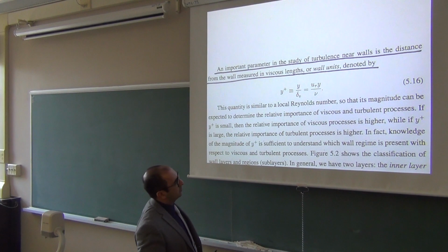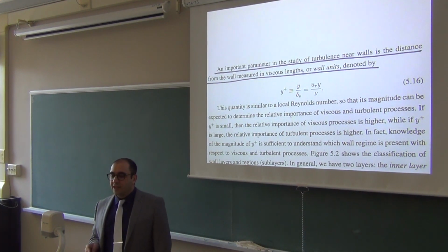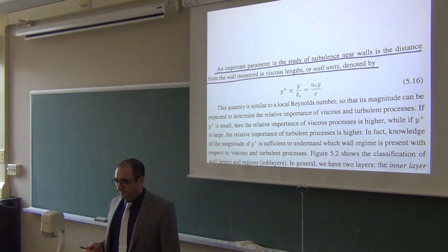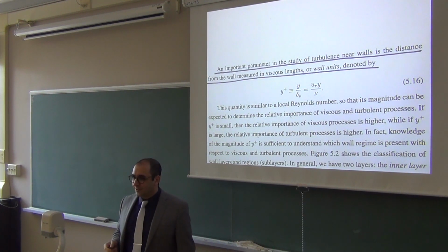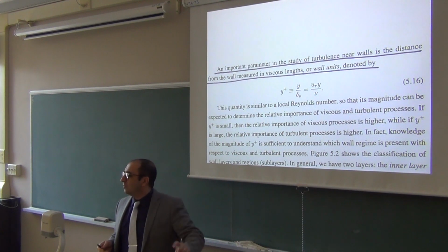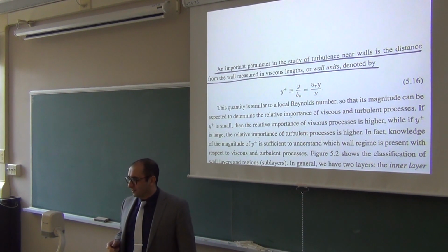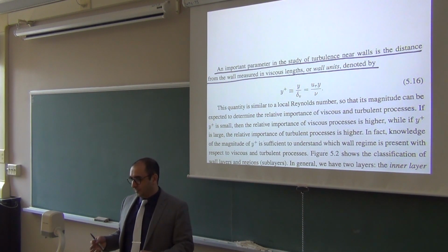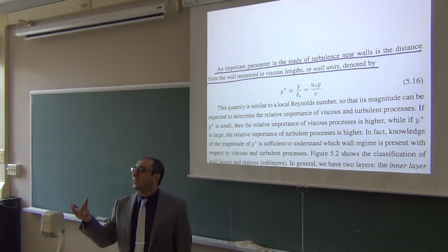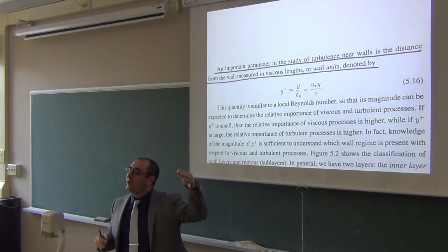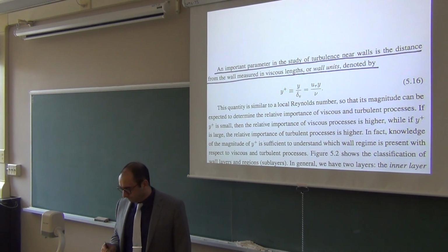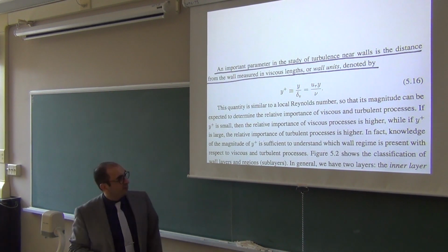When you normalize the wall flow problem, you say, okay, my y plus is 16, for example. He immediately knows that I'm 16 times away from the length scale of viscous action. He doesn't need to know what each individual height was or what the specific problem was, but in a normalized sense, the statement helps him understand how far into the turbulent region I was. That's how useful normalization is.